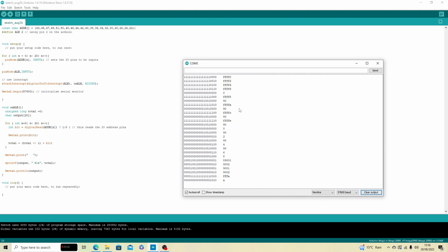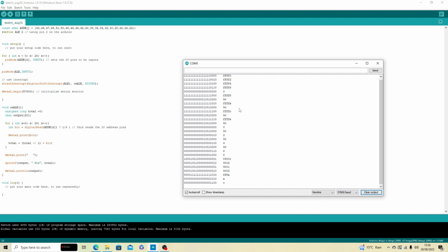So to do that, I'm going to now add an EEPROM chip, and the one I've chosen is the 27C512, as this uses a 16-bit address, and we can code in the jump statement to that EEPROM. So that's what I'll try next, and connect that up.